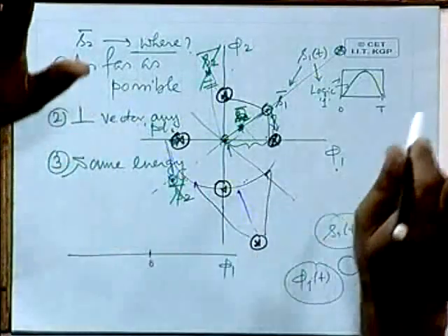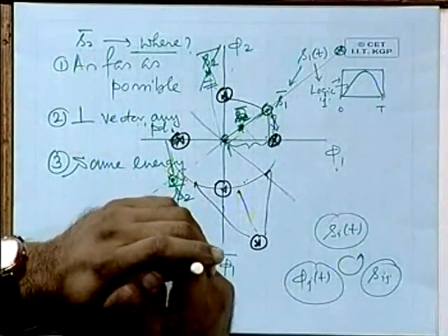This signal space diagram can be utilized for designing modulation schemes, even for picking up the modulation points or the signal vectors such that the average transmission power is rationalized. And not only that, a very important issue is also to design the points, place the points such that the corresponding decision making process in the receiver is going to be the best possible. Only thing is that we have to formalize what is that best procedure.